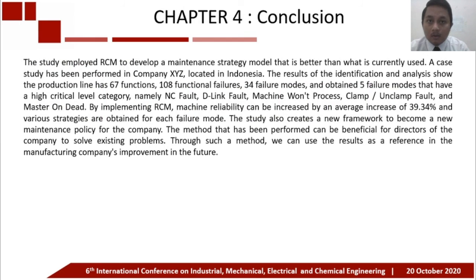This is the conclusion of this research. The study employed reliability-centered maintenance to develop a maintenance strategy model that is better than what is currently used. We get 67 functions and 108 functional failures, 34 failure modes, and obtained 5 failure modes that have a high critical level category. And by implementing reliability-centered maintenance, machine reliability can be increased by an average increase of 39.34%, and various strategies are obtained for each failure mode.